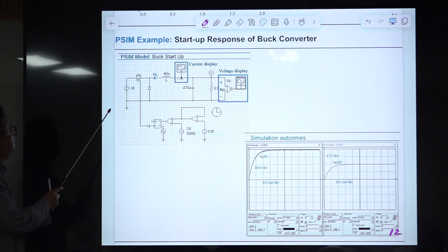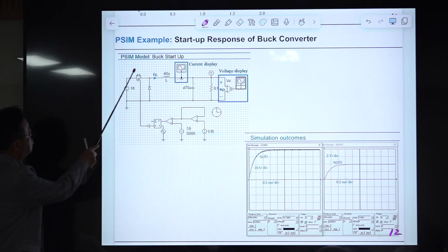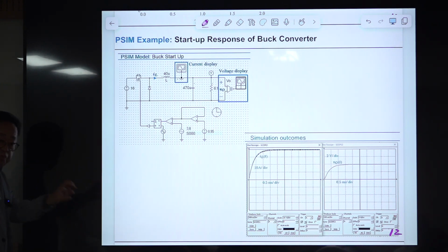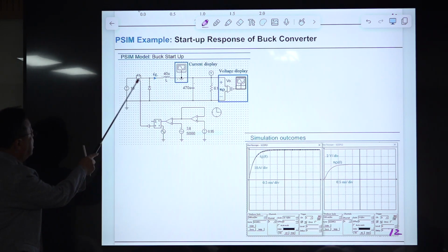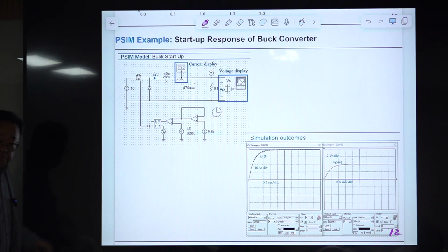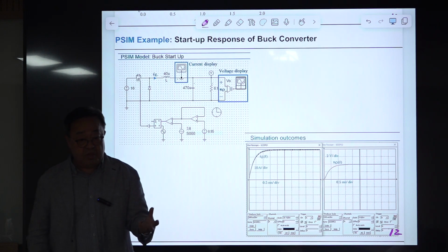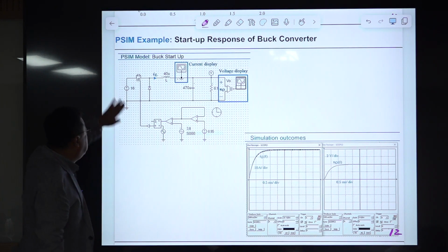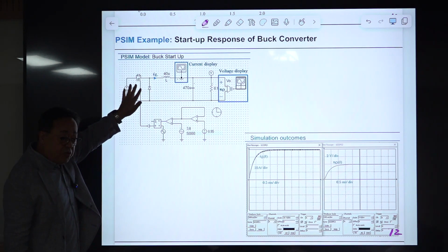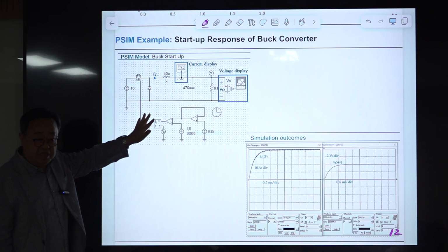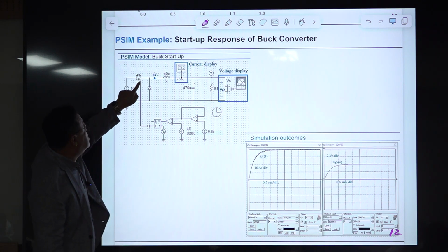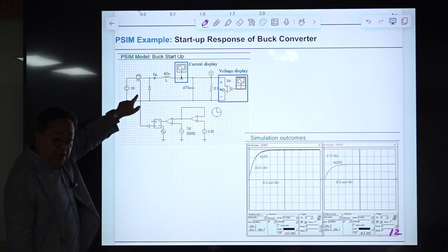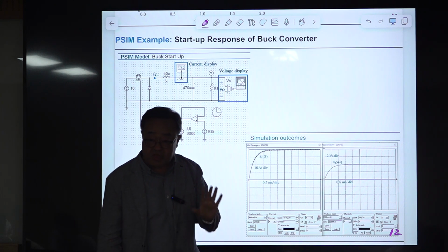Okay, and anyway, this is for a converter. So this is a MOSFET switch. You are using a MOSFET switch all the time, and this is the switch, drain, source, gate, and this diode is a built-in diode. If you have a MOSFET, then there is a diode. They come all together as a pair. Okay, you cannot make it without this capacitor for this MOSFET for the practical reason. If you avoid this, the performance of this MOSFET is very poor. You cannot use it in practice.